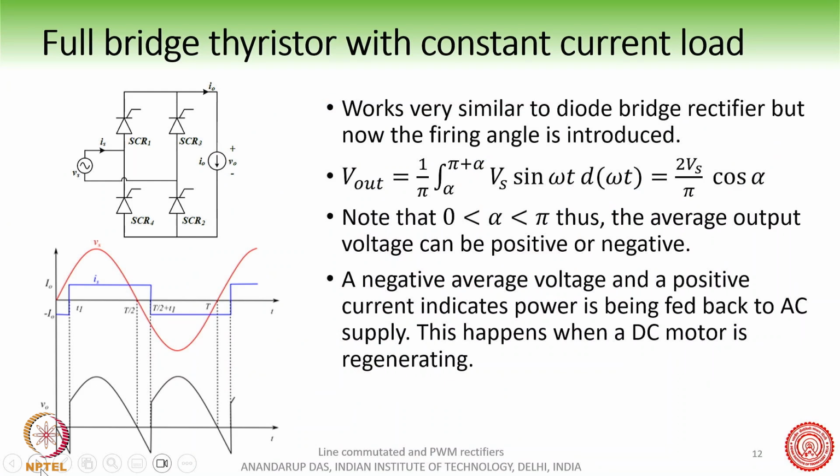Now, when you have a large motor load, of course, then this RL load we replace with a constant current load, right? The reason being that the time constant of this RL load is so high as compared to the 50 Hz AC sinusoidal impressed voltage or the source voltage. The AC waveform alternates every 20 milliseconds. Okay, the time period is only 20 milliseconds.